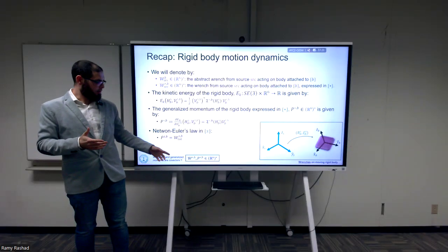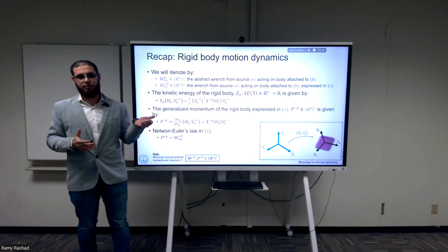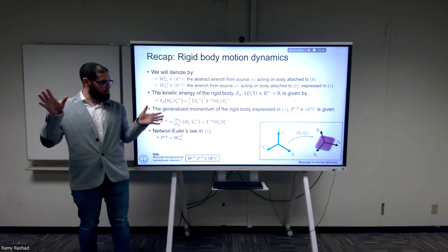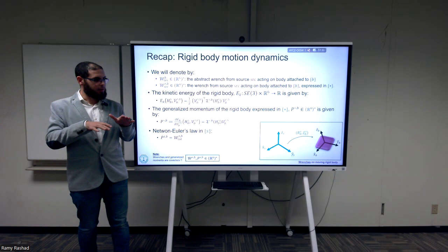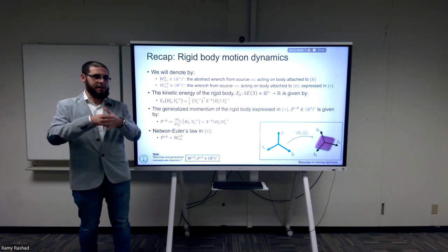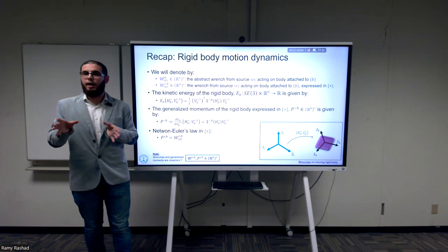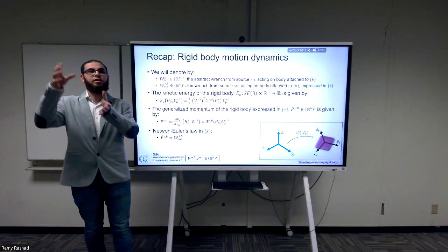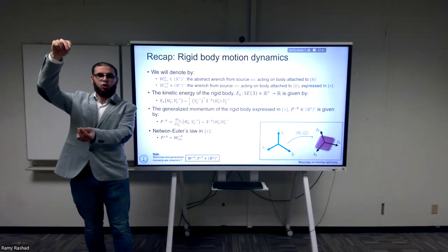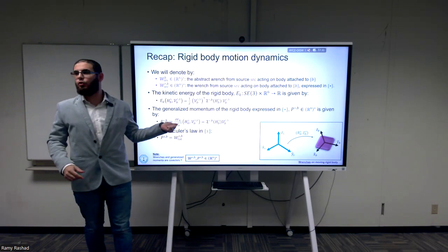The hard part is that you can no longer think of wrenches and momenta as vectors. And this is where linear algebra really breaks down. I can speak about this for a while, but the fact that you have something called vectors and covectors is completely overlooked in many books and many fields of study. People usually write vectors and covectors both as vectors, and then you don't know what's the nature, because both of them can be written as an n-tuple, as some numbers below each other. You're going to see clearly here that we can no longer do that.